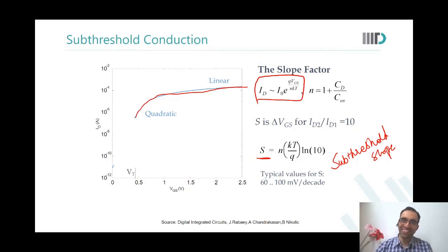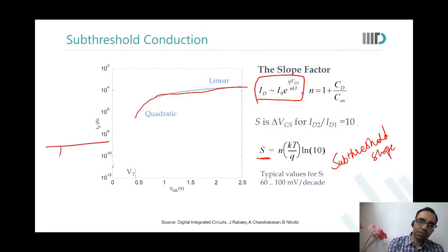Because as Gagandeep said, it's almost like a PN junction, right? But I'm confused as to where a PN junction will be formed because before VT, there's a depletion region, right? Depletion region का मतलब क्या है? That there are no charge carriers. Where would a depletion region be formed? Where there is N plus type under the gate, which is P. So this is a PN junction, is it not? Yes. Similarly, there is a PN junction here.